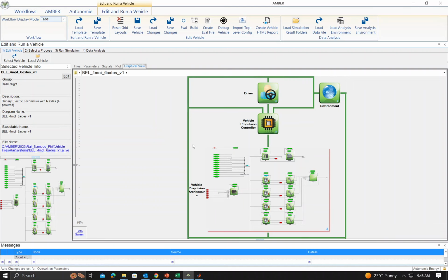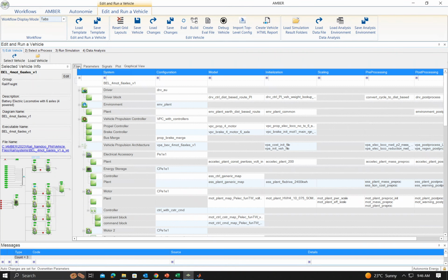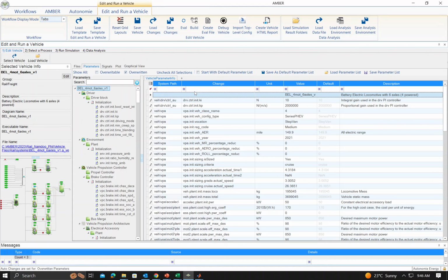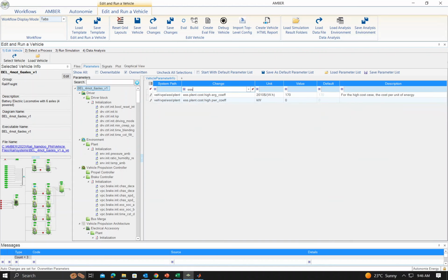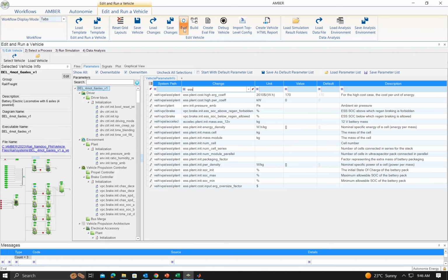There are many components, but in today's video I will be focusing mainly on the battery side. I wanted to quickly show you some of the battery parameters that we have used here. If you click on the override table and then click eval, on this screen we can only update the discrete input variables required for simulation. It does require some maps which are in vector format, and for changing those data we need to modify the initialization file, which I will show you in a short while.